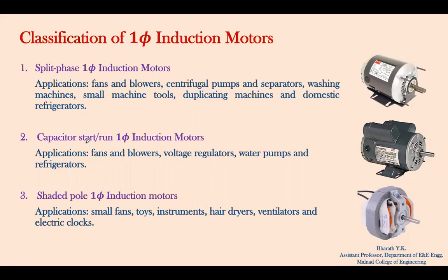Capacitor start and capacitor run single phase induction motors are used in applications such as fans and blowers, voltage regulators, water pumps, and refrigerators. In domestic water pumps, which are used to pump the water to the overhead tank, capacitor start single phase induction motors are normally used. Shaded pole single phase induction motors are used in applications such as small fans, toys, instruments, hair dryers, ventilators, and electric clocks.